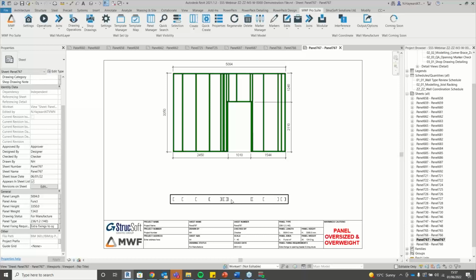And we have a question from Ewan James. Could you use Dynamo to run clashes between walls and internal components to place marker lines to create fixing blocking members? Yeah, so I've done similar concepts in the past, and I think it's a solid maybe, because I know that you can use Dynamo to identify these instances.